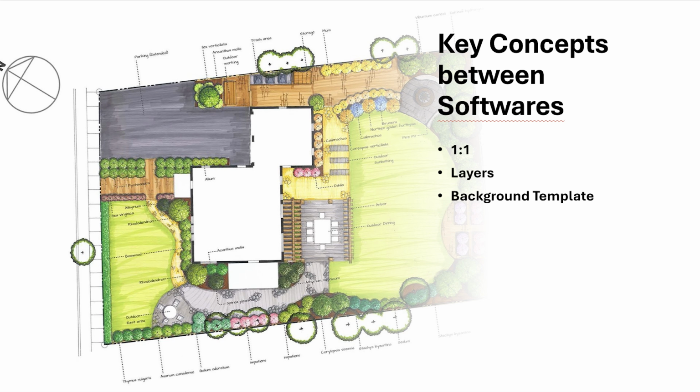We then traced the image and scaled it one-to-one using the Scale tool. Scaling one-to-one means that we are scaling the drawing to real-world dimensions, where 1 foot on the paper equals 1 foot in real life. Once the image was imported, we were able to move it to its own layer.